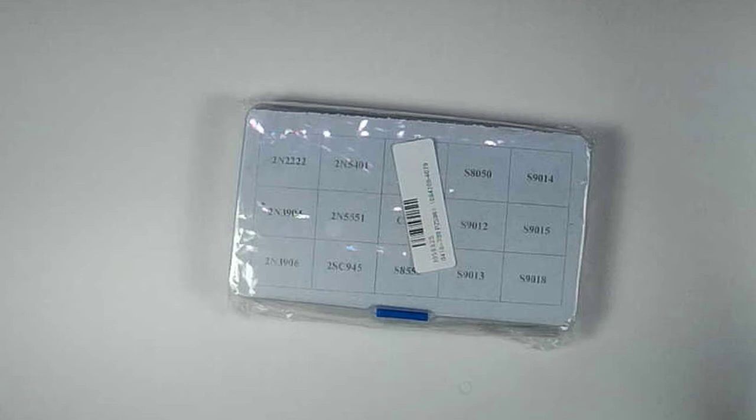This all will jump here, go here, jump here, and then these three will be connected to the Arduino. When you connect it to the Arduino, we have to connect these LEDs directly to ground, because ground is the only lead that we can actually switch. This has to be 12 volts and we cannot change it.